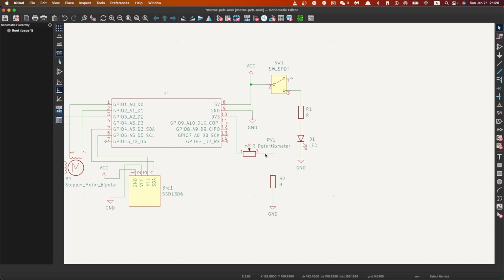So there should be something pointing from, let me check which one I was using. I was using D9, so that would be the thing pointing from D9 to somewhere. Will this be here? Of course not, right? Because if it's here, it should always be 3.3 volt, and if here, it should always be 0 volt.